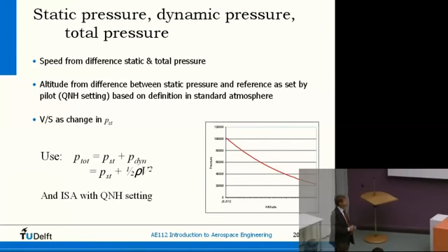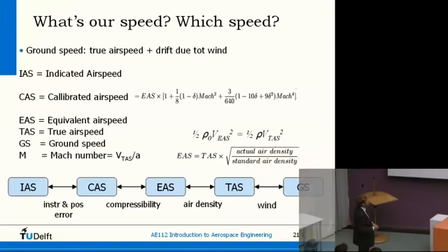And during the flight that's the main important thing, but as soon as we get lower, where there are mountains or we want to land or take off at some point, then you need to know the pressure at sea level before you can tell what your actual altitude is. The radio altimeter only works at the very last second. You cannot use that a few thousand feet up. So the only way to do that is to know the reference level, and that is called the QNH setting. So you need to set the QNH, and then everything works for the air data computer.